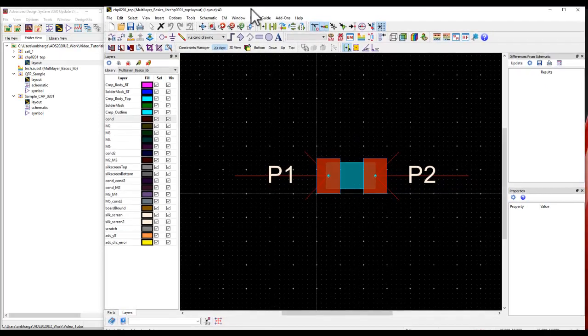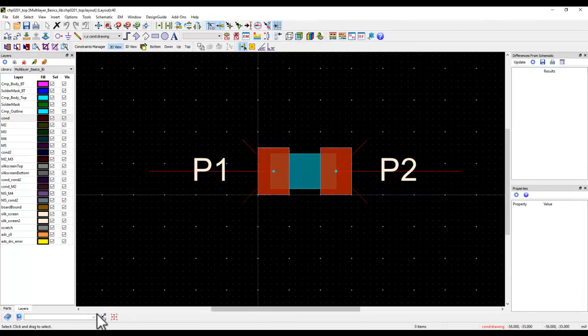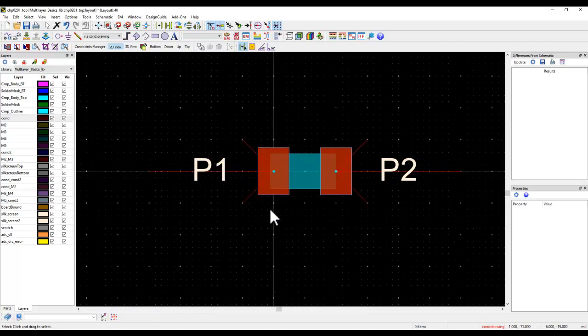So during component creation, you can place the origin by simply clicking on this icon and clicking, and now you can see the crosshair origin point has shifted to this node. Whether you want to keep it on a pin, or some people want to keep it at the center of the component, it's your choice. I just prefer to keep it at the pin location here. Now I can save it.